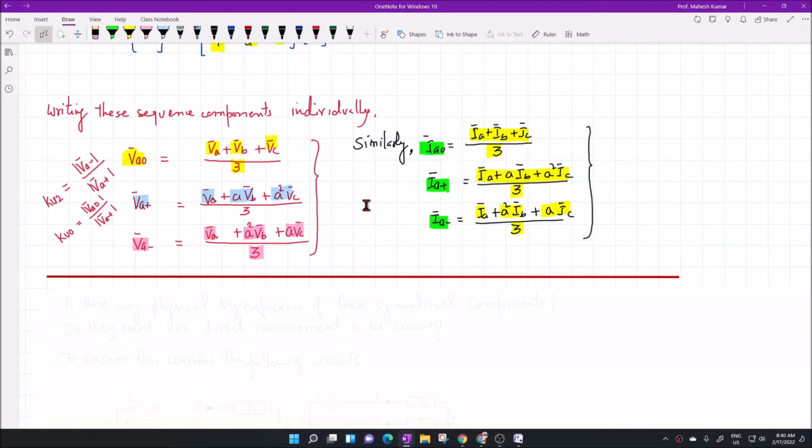So when you generate the AC waveform from the generators, because of the finite number of teeth in the armature, in the stator, the output voltage is not perfectly sinusoidal, rather it has some distortions. Because of that, this voltage is passed over transmission line, transformer, then transmission line, then distribution system. And when it comes to the distribution side, there could be 5 to 6% unbalance in the voltages.